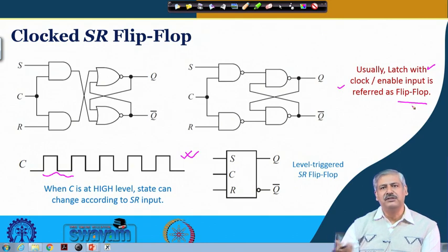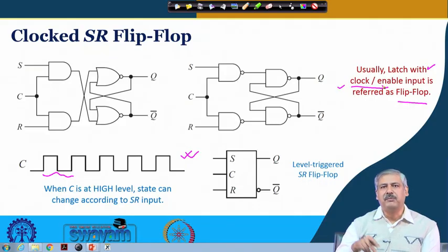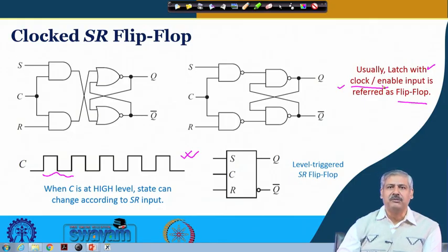Okay. But then you will see that in the text it says latched SR flip flop. So, basically latch type SR flip flop. So, basically they are referring to a latch as a flip flop, but in other texts generally speaking, a flip flop means the presence of a clock, and a latch is just the last stage, where the memory part is, where the value is latched into. Okay. So, that is the way the distinction is often made in this particular field.